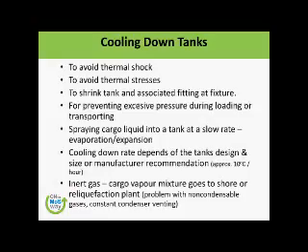Now while we are discussing the gassing up, the second process after the gassing up is the cooling down. That process goes hand in hand, where we will do the gassing up, we will do the cooling down, and of course we'll avoid the thermal shock. So once we are gassing up, we are slowly cooling it down as well. For cooling down, normally we use spray rinse. We diffuse. So I will tell you about the cooling down also.